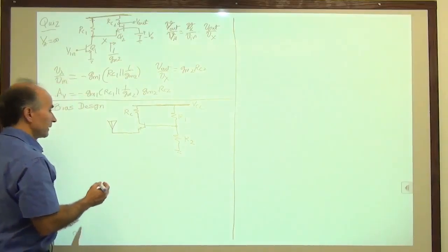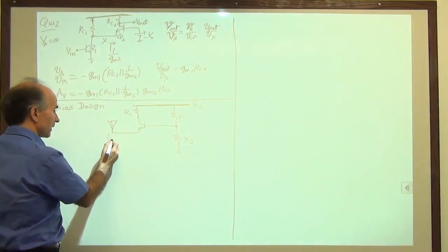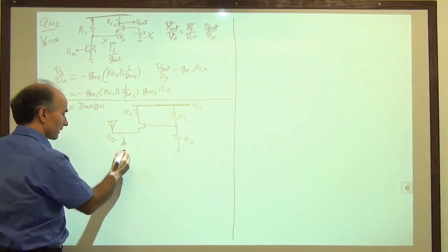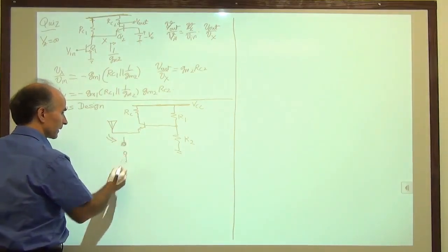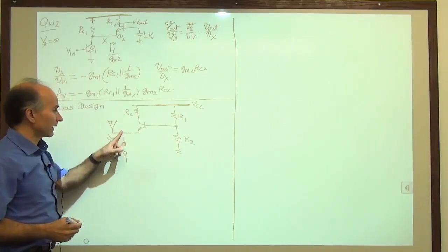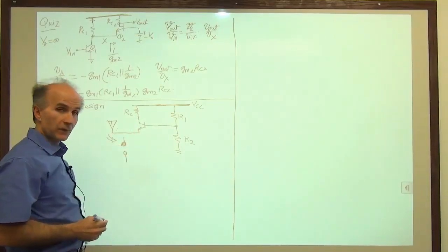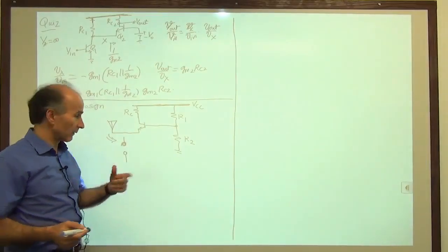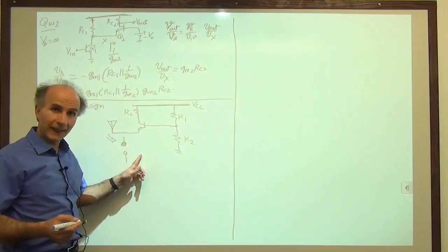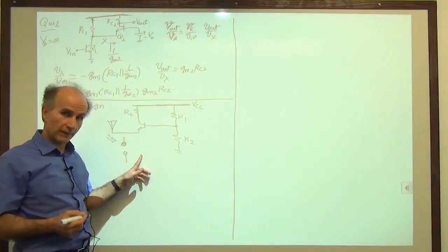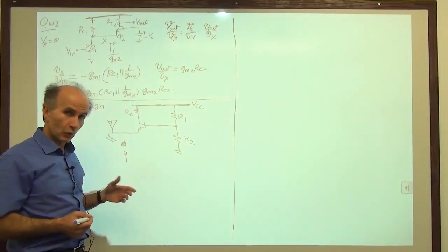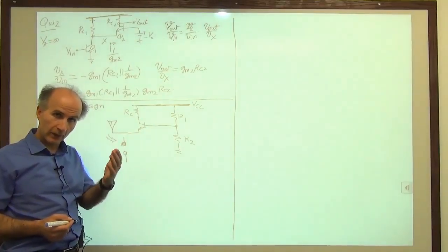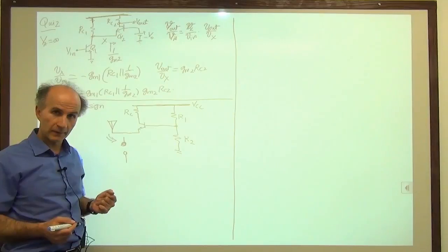All right, so if indeed this antenna is equivalent to an open circuit, I'll just show it like this. So that antenna doesn't allow us to have a current this way. We have to have some other device that we add ourselves from this emitter to ground to carry the bias current of the transistor. So we should be looking for some sort of 2-terminal device that is capable of carrying DC currents.